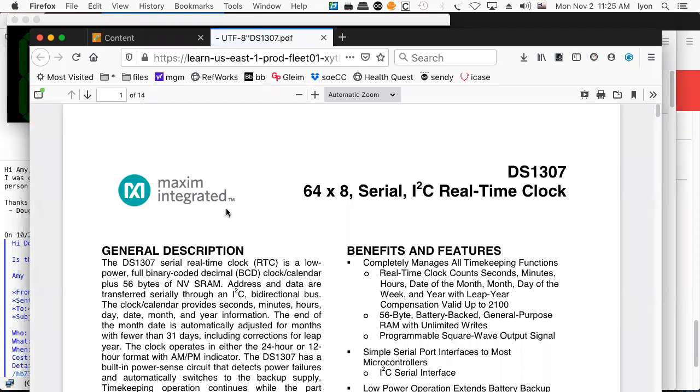And Maxim was well known for creating exotic mixed signal integrated circuits. That was their forte. In case you're wondering, mixed signal means a combination of analog and digital in the same package. So they'd make an RS-232 to TTL level converter, which would essentially take 0 to 5 volts and convert it to plus minus 10 volts using a little internal charge pump and put the whole thing on a chip. Stuff like that. Really useful, kind of expensive little chips that you could integrate into your project and would help jumpstart things.